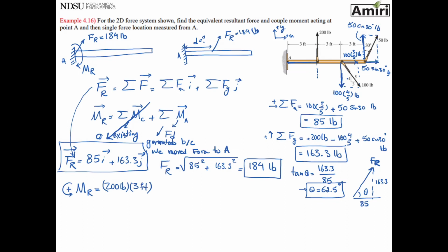And if I pin at point A, my force is trying to rotate the beam counterclockwise, which agrees with my sign, so it's going to be plus. So I'm going to leave it at that. Next, let's go to the 100-pound force. I have already resolved it into two components. One of the two components, which goes through point A, doesn't create any moment.